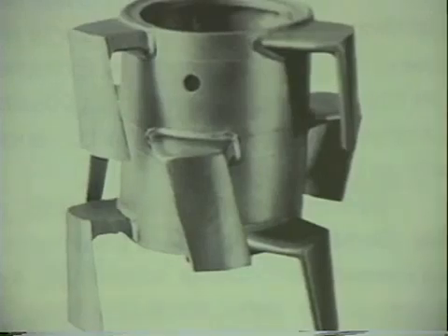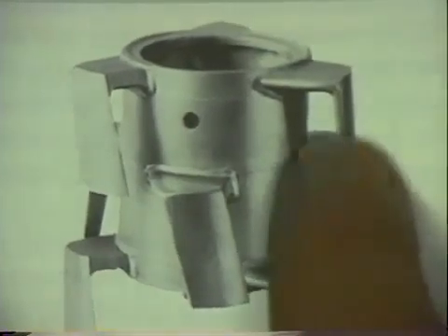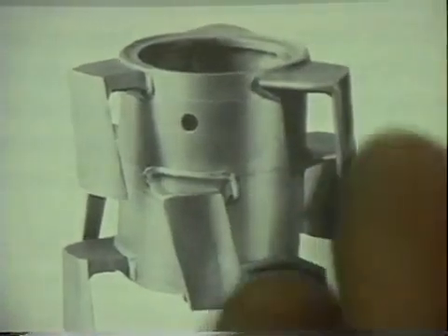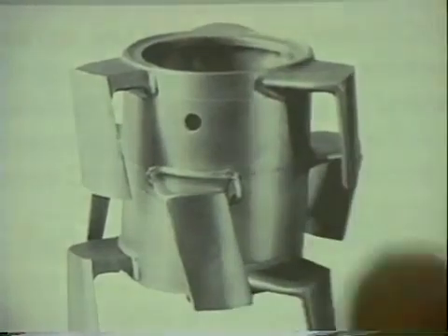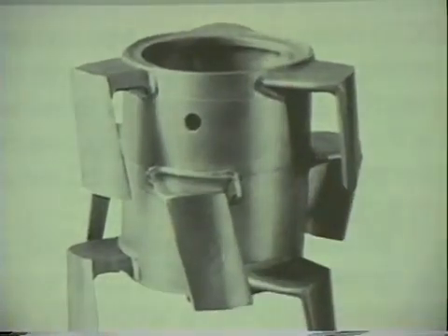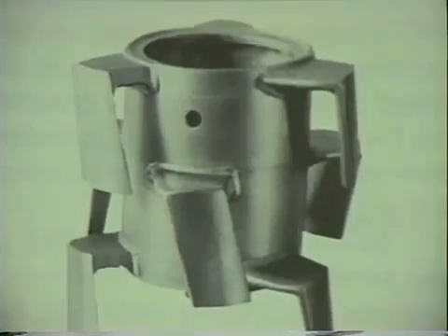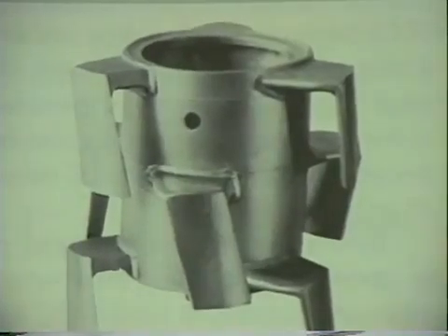And that backflushing disrupts any type of pulp mat formation that may occur on the face of the screen. Okay. So that's a really, really important part of screening. It's that backflushing and preventing of the blinding of the screen. So we have to have that.